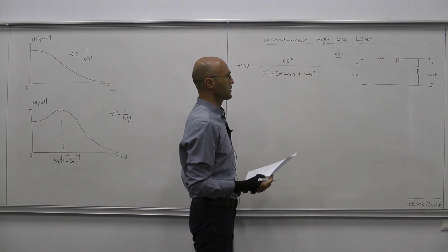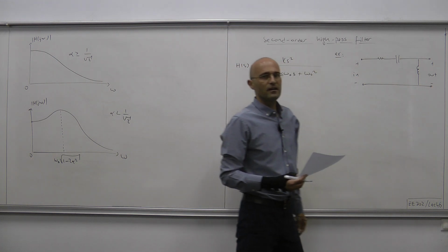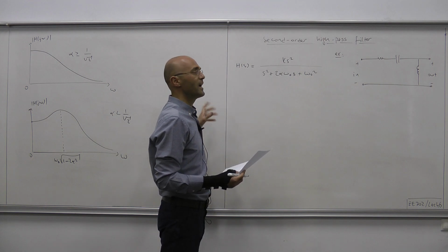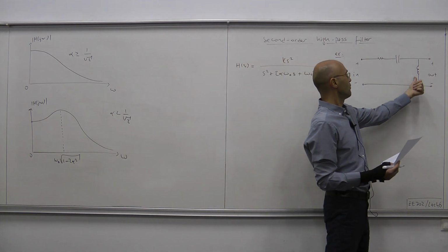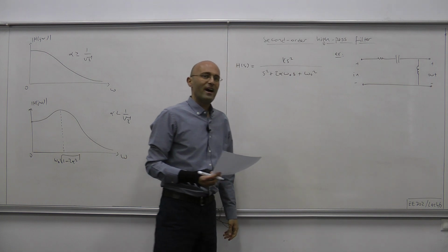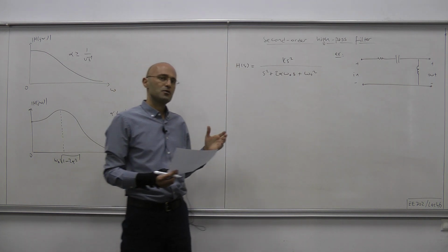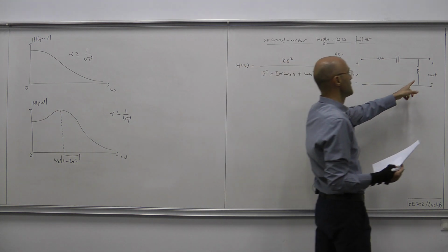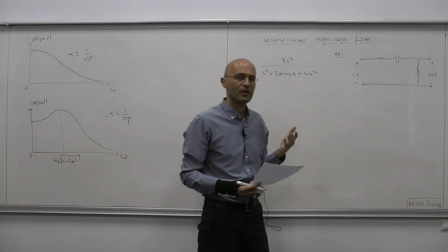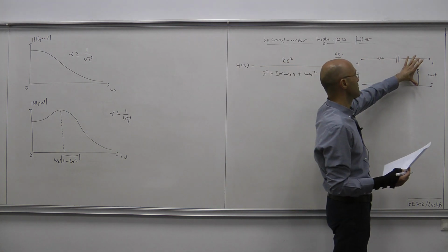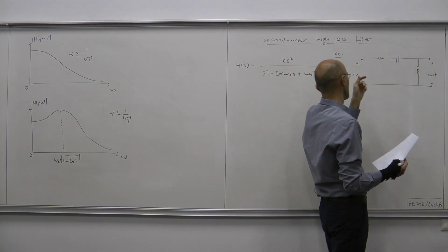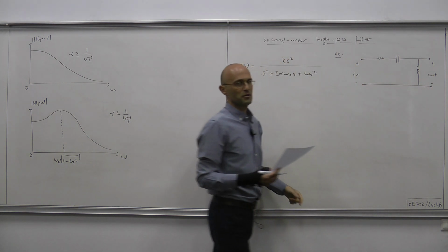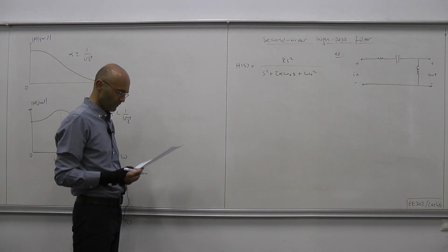So at low frequencies, the output voltage is insignificant, and when the frequency is high, again the impedance of the inductor j omega L becomes larger and larger. So at very high frequencies, the inductor starts behaving like an open circuit, and clearly most of the input voltage will appear across the terminals of the inductor.